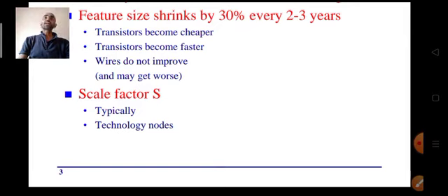The reason being that whenever we scale down the device, it is not always a dumb shrinking. When I say dumb shrinking, it means that it is not like theoretically you have calculated that to reduce the device area to half, you have to shrink the device dimensions by 0.7. Practically, it is not so. Whatever you have calculated theoretically roughly applies to the practical thing, but the device dimensions may be somewhere near that. Sometimes it becomes 0.6 and sometimes it may become 0.8 as well, onto the next technology.